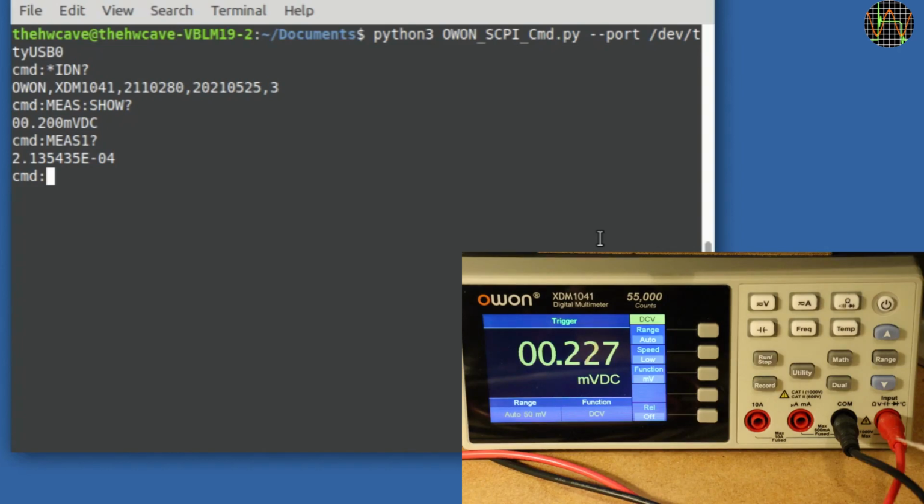The command is CONF:VOLT:AC auto. It works, but the meter returns this weird OK with \n or new line control characters. That's new. It did not do that before. According to SCPI, only commands that end in a question mark should return anything.